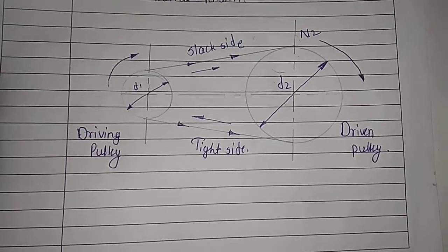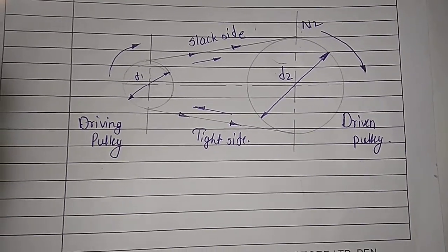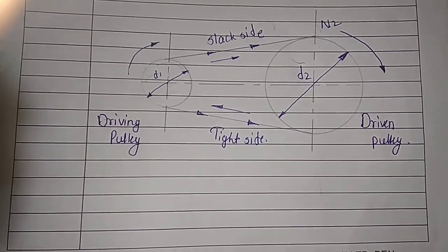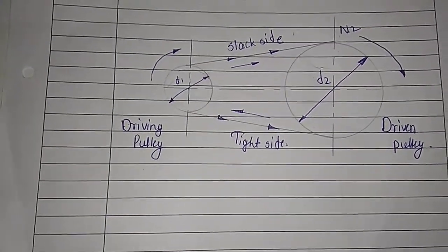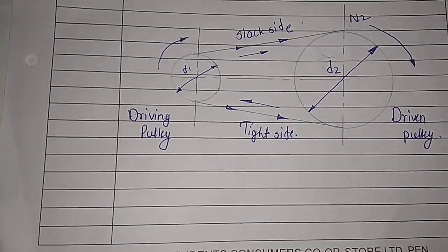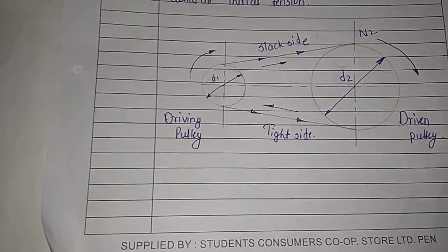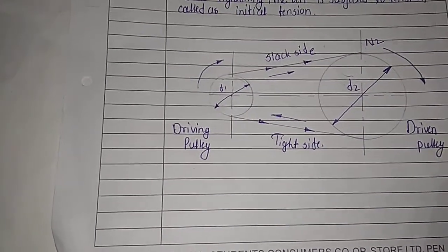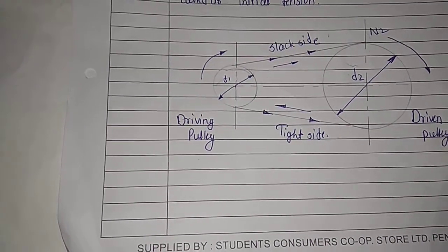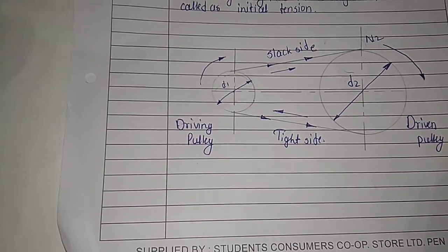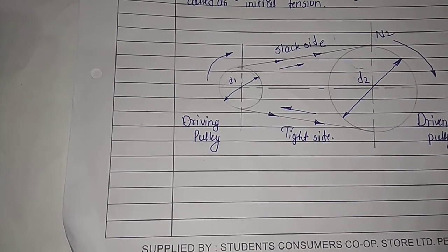They are also similar to the law of belting. The law of belting states that the center line of the belt, as it approaches the pulley, must lie in a plane perpendicular to the axis of the pulley, or in the plane of the pulley, otherwise the belt will run out of the pulley.